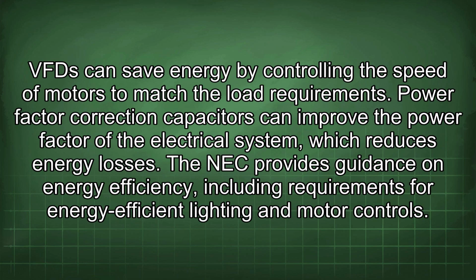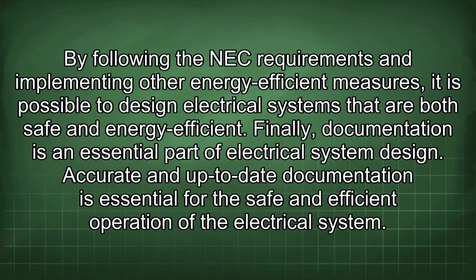VFDs can save energy by controlling the speed of motors to match the load requirements. Power factor correction capacitors can improve the power factor of the electrical system, which reduces energy losses. The NEC provides guidance on energy efficiency, including requirements for energy-efficient lighting and motor controls. By following the NEC requirements and implementing other energy-efficient measures, it is possible to design electrical systems that are both safe and energy efficient.